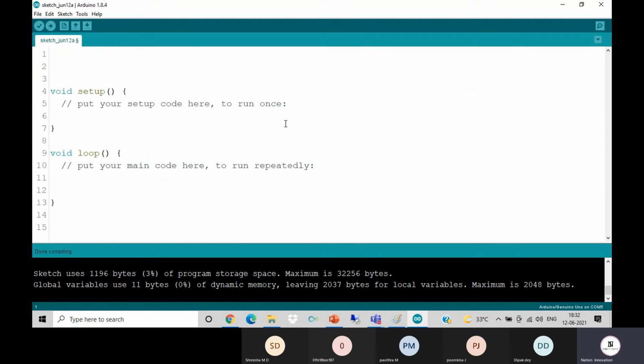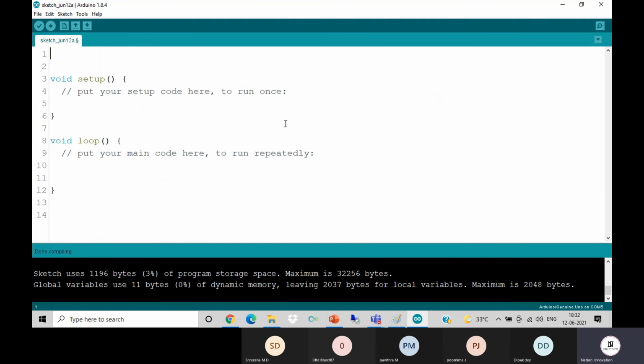So for an LCD, there are multiple functionalities available to control it. To write something to the control register, there is a sequence of steps. First, the enable pin will go from a high pulse to a low pulse for a particular time cycle. Then we are going to send the control data first. Then we are going to send the data which we want to display. So this is a little bit complex for newcomers to handle. That is why Arduino also gives the availability of different libraries. And in this case, we are going to use the help of a library to interface the LCD itself.